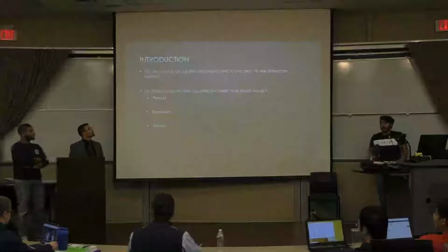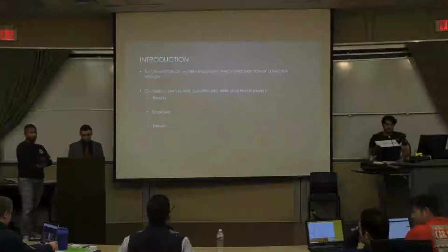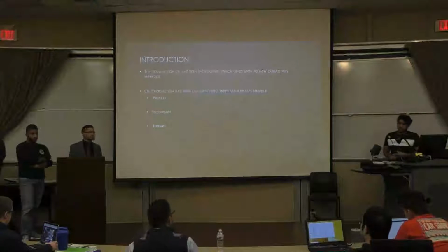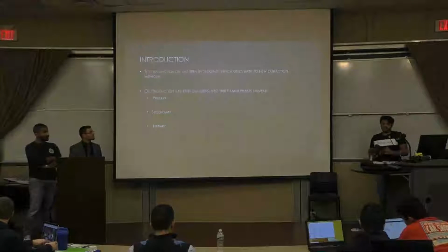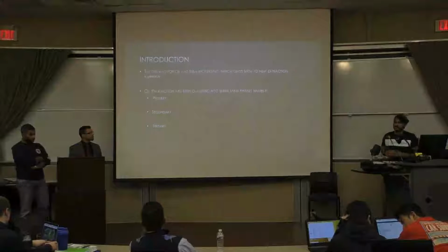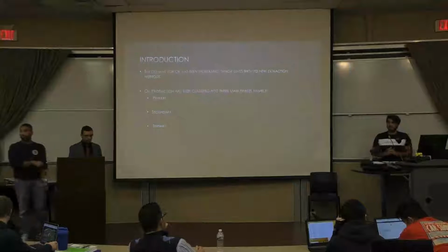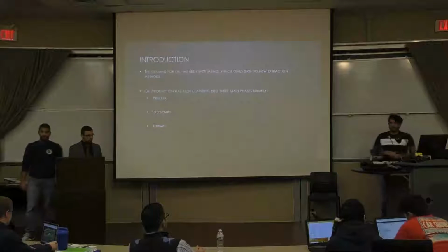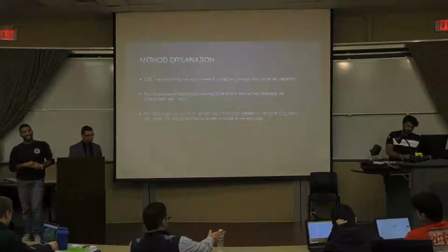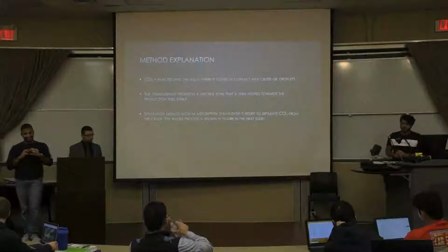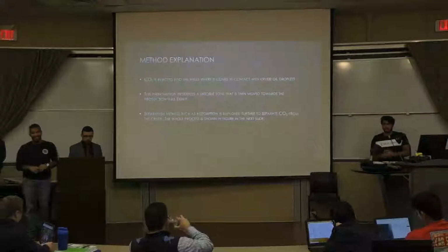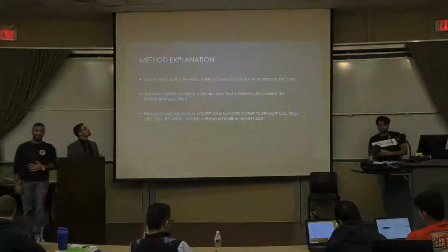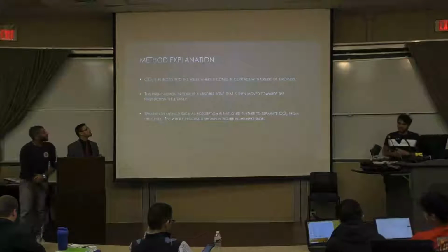Oil production has been classified into three main phases, which are primary, secondary and tertiary. Secondary recovery is used when the primary method is no longer available and can produce 40% more recovery than primary. This method includes the injection of CO2 in a well containing oil droplets, which then forms an oil mixture that is pumped to the surface by the producing well.